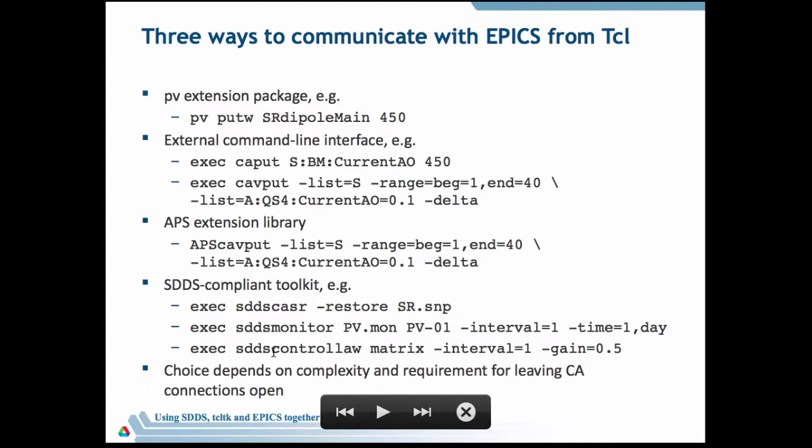Control law is actually a feedback command. I took the control law name from one of the elementary books, control law, U equals KX type of control law. What happens in that case, K is a matrix. The matrix, by virtue of it being an SDDS file, everything is named. So if the columns are named from the PV that you want to control, then all the information is known. You have an inverse matrix, you have the PV names, and you also have to supply a string column for the actuator names.